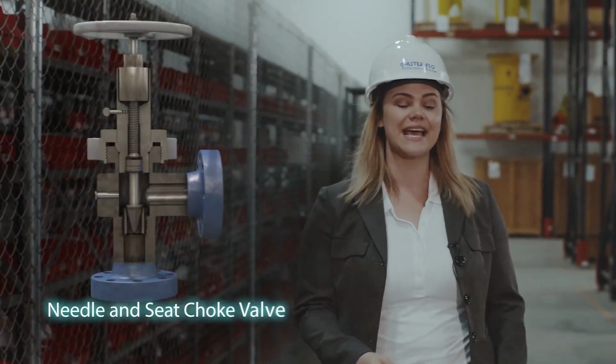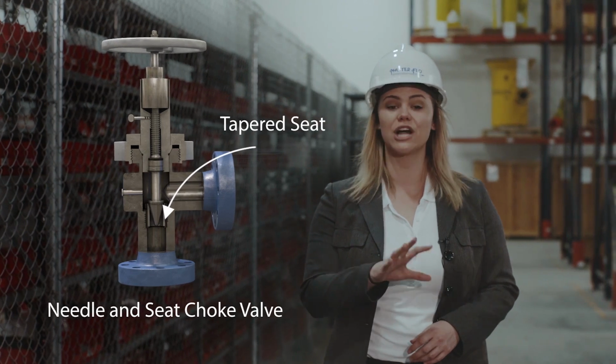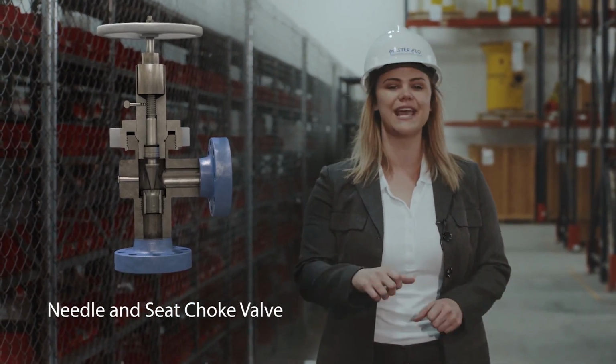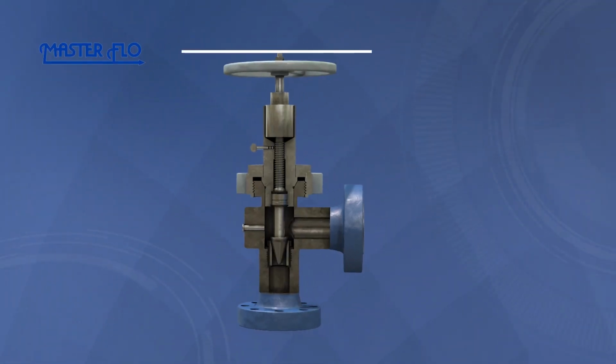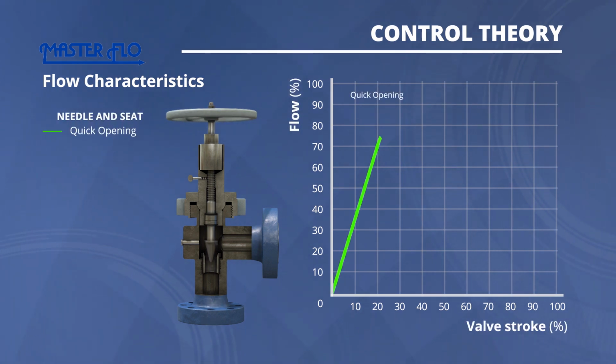The needle and seat has a tapered lead on its stem to restrict the opening by closing the tapered seat. The throttling is achieved by rotating the handle on its rising stem. Due to the tapered design of the needle, a small rotation of the stem handle can cause significant change to the orifice opening. This choke design doesn't provide a high degree of control. When the choke is open halfway, you experience full flow, losing most of your control.